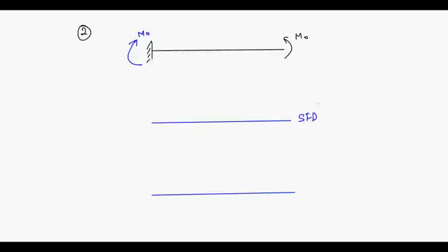The shear force diagram is nothing but W is equal to dV by dx. Throughout the span, you are not having any loading, so your shear force will be constant throughout, isn't it? And what is that constant value? It is equal to 0, because there is no reaction here, so your curve will not take any jump or anything. It will remain 0 throughout your span. I think you are able to understand. Last lecture, last part also, I think we did the same thing.